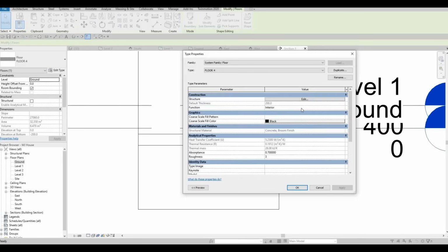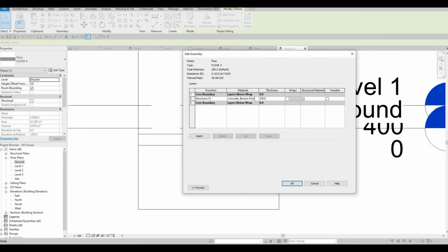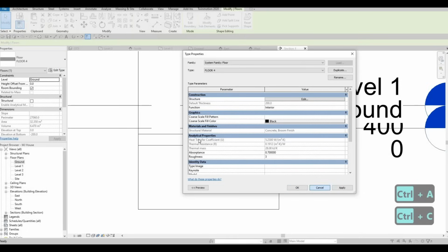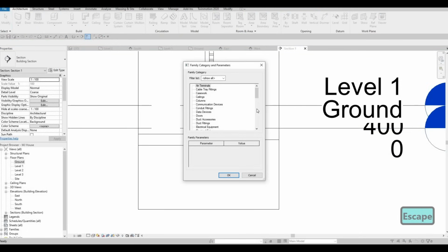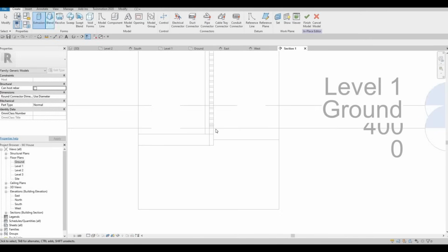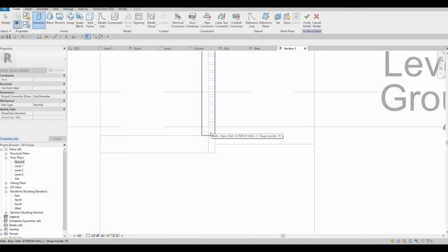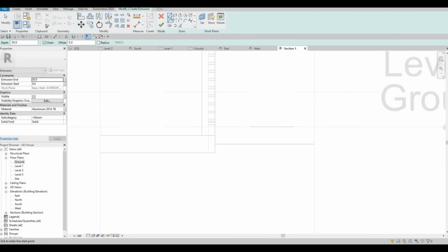We just need to know which is the finish. So I'm gonna copy this finish, and then I'm gonna use a model in place in order for me to make this one nicer. And then pick a plane. I'm gonna choose this wall as my plane, and then after that I'm gonna make this one curve.